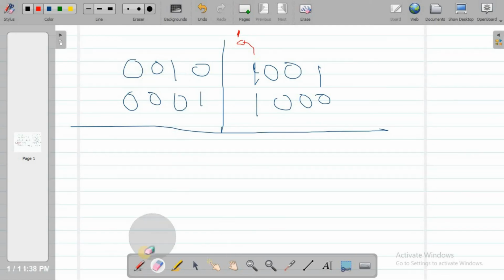So if you have a carry after adding this side, an extra carry, a 1 that comes out here, the result won't be a BCD, and you must add 6. Let's take this example. When I add this one, I have 1, then 0, then 0, then 0. You see, I'm going to have a carry of 1 here. So automatically this one is not a BCD.